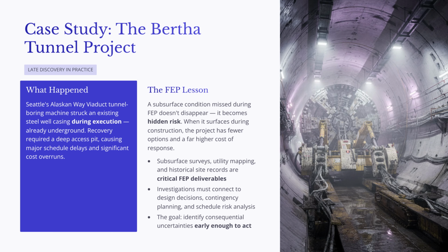For front-end planning, the lesson is not simply that underground conditions are risky. The deeper lesson is that existing conditions must be investigated, documented, and carried into the project risk register before the execution baseline is approved. A subsurface condition missed during front-end planning does not disappear. It remains embedded in the project as hidden risk. When it appears during construction, the project has fewer options, less flexibility, and a much higher cost of response.